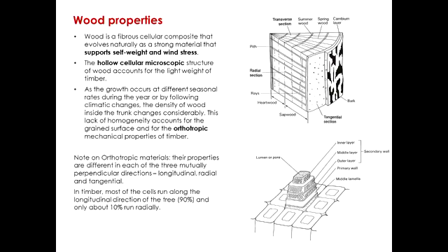Now, there is another very important thing you need to know. The cellular structure of wood is not only non-homogeneous in the three different directions, it's also a hollow structure. So it means there will be moisture inside. And you'll see in a moment why I'm mentioning that there is moisture inside, because we'll need to season the product before using it for structural purposes and also for cladding and flooring.